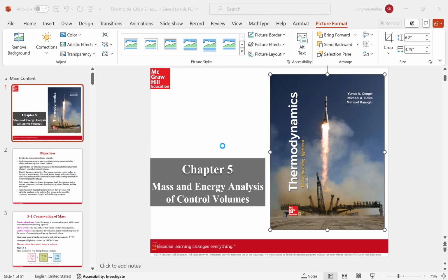And what this simply means is, check this out. This shows you the velocity. This is called the normal direction, which means it is perpendicular to the surface area. So the component of velocity which is perpendicular to the surface area, multiplied by the area dA, multiplied by the density, gives you the total mass that is crossing the control surface.